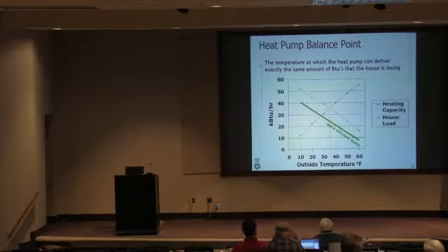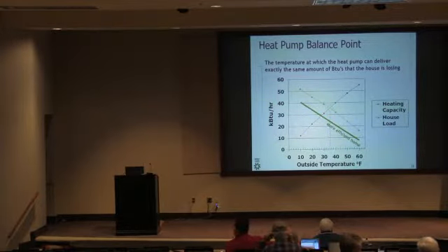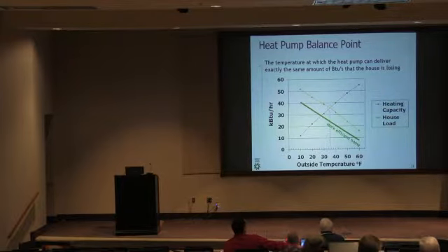Heating on the other side, heat pumps, this has always been one of the big downsides to heat pumps is this balance point issue and when you have to run the backup electric resistance heat, how expensive is that to do? And it is nice that if you have a super insulated home and a super high SEER heat pump, you can get down to balance points that are pushing 0 at this point, but down at least into the teens.